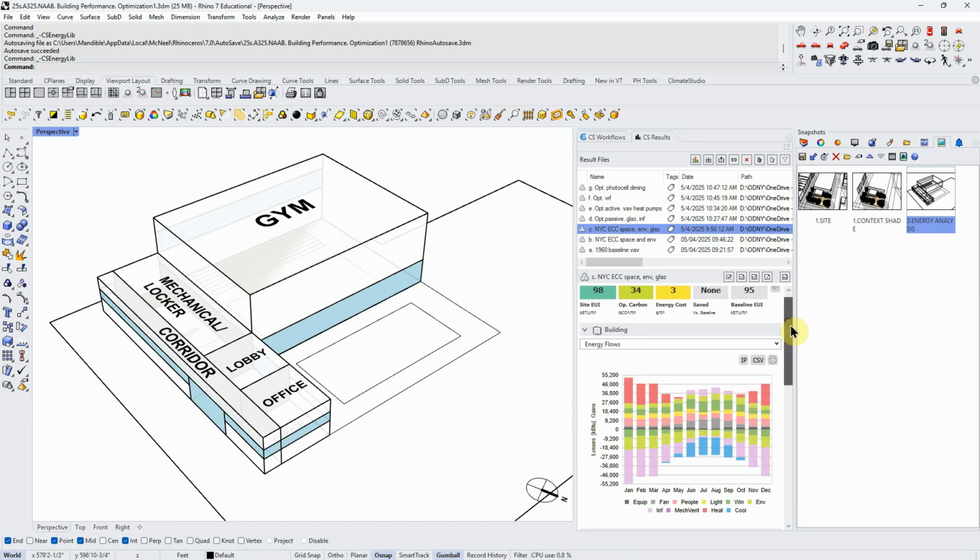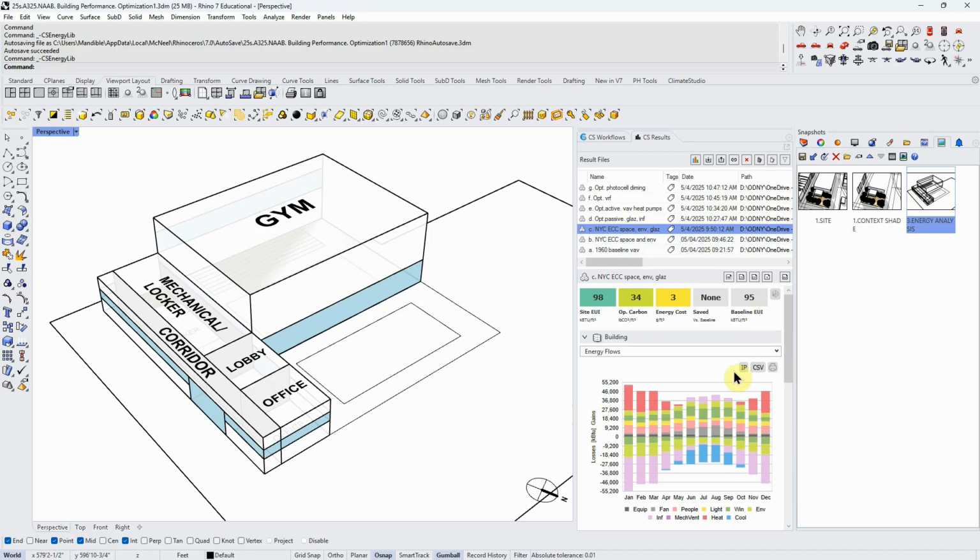And so there's lots of things we can do. What I did next was I improved the infiltration level. Now that's something you can't just arbitrarily do. I know about this, and so I actually cut it in half. You'll see that goes down a lot. I improved the glazing package, so I made it have a very low U value, and I think I lowered the solar heat gain coefficient. Anyway, so I did some things like that and was able to lower my site EUI further. I kind of felt like that was the most I could do with passive things, considering the envelope and the windows.